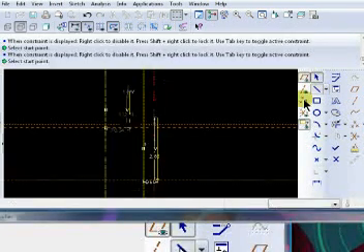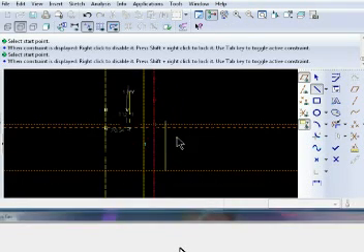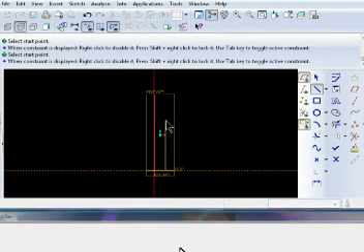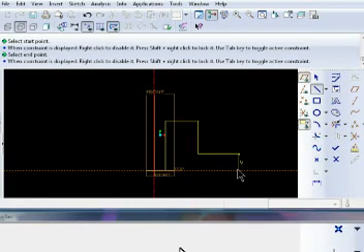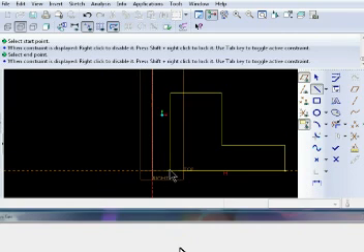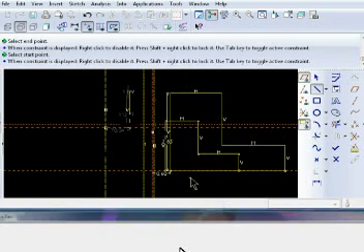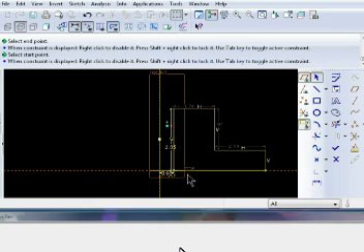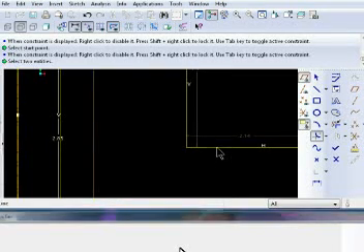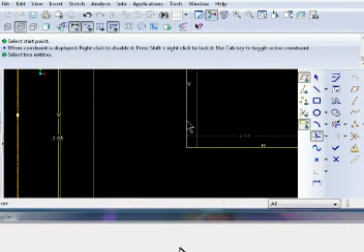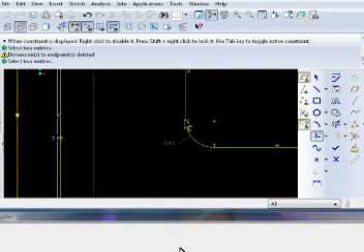And now we go back to sketching the profile of the cross section. As usual, we will draw the profile with very little attention to accuracy, which will be established later. We need to add a fillet to this line here. So click on the fillet tool, and you need to select this line and this line, and there is your fillet.